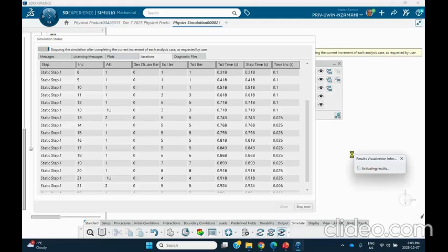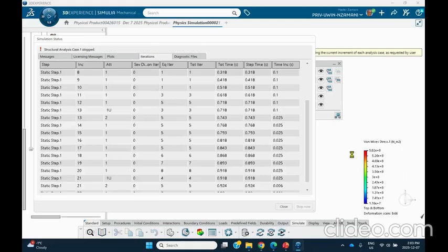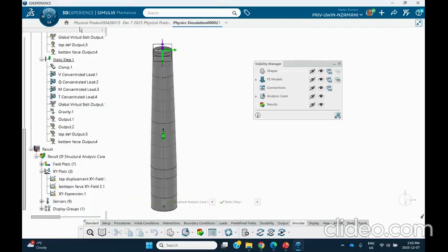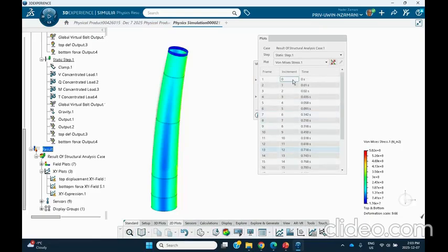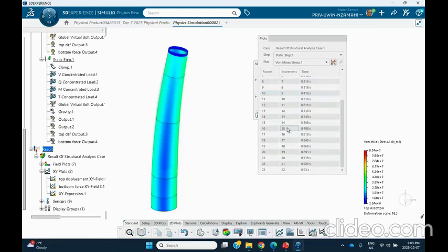Trying to stop and recover whatever data it has up to that point. You see, that legend on the right disappeared because that was from the previous stop. We say okay. First of all, let's go to the results. You have to go to the results here because you stopped it; otherwise, you would have gone there automatically. There we are. This is initially, and then gradually elastic. Remember the yield strength was 345 megapascal, so it's 87 right now.